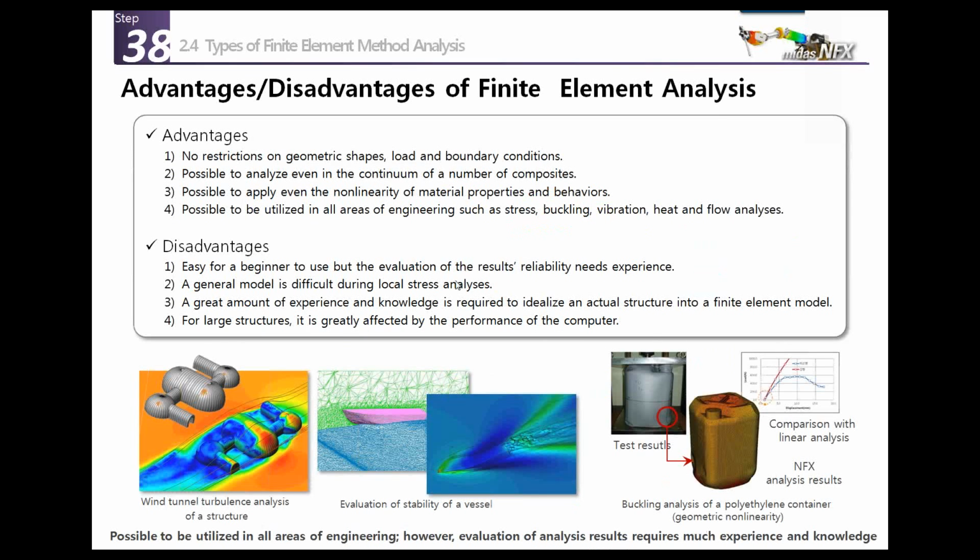Now let's talk briefly about some advantages and disadvantages of the finite element analysis. The major advantage is that there's no restriction on the geometric shape, on the load and the boundary conditions. So you can really have a model which is very close to reality, and you can analyze very complex problems that cannot be solved theoretically.